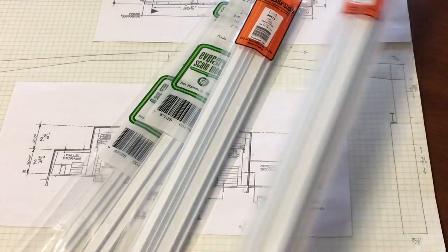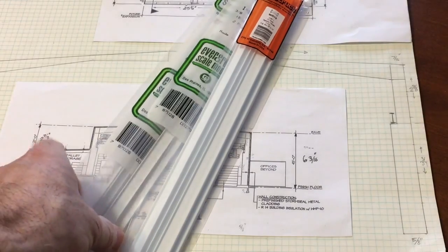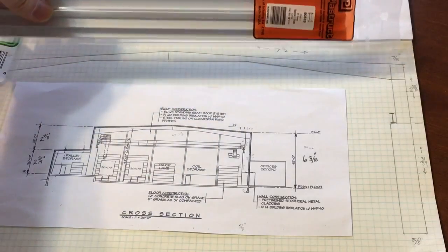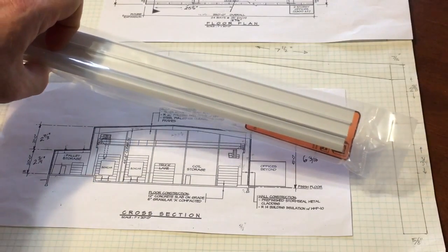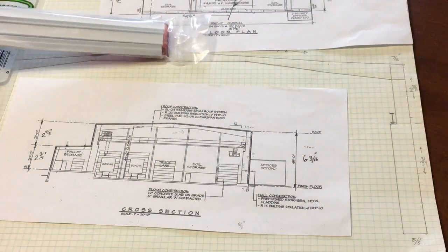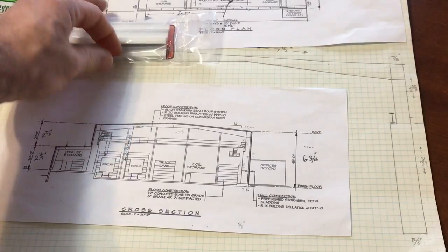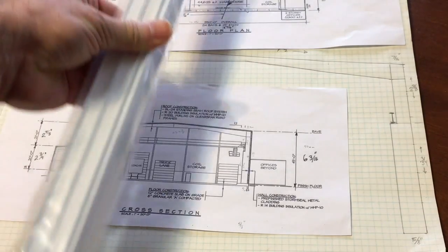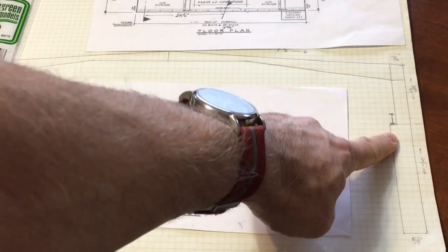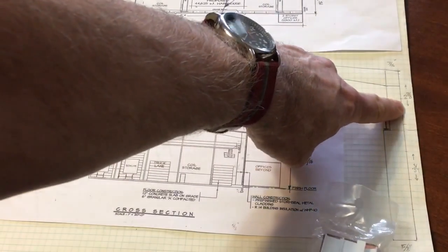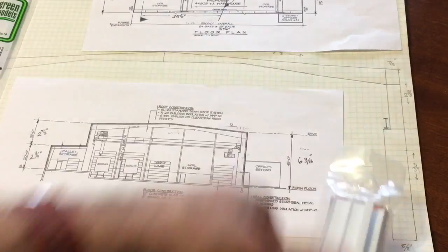As far as the roof beams are concerned, again, I thought 7/16 inch is about right, and I don't mind if it's a constant thickness across. It's about the right thickness at the center of the roof, and at the same time, where there's the notch here for the crane rail, the width of the column decreases to about 7/16.